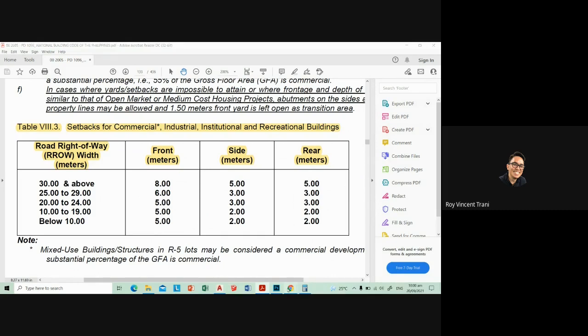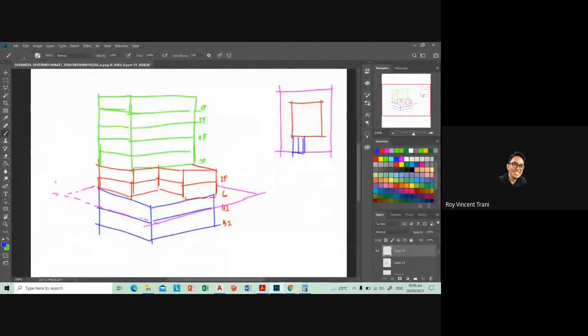But as we mentioned last week, let's say Bilaran Road is here. I'll just call it B Road and M Road. So Mindanao Road and Bilaran Road, this avenue, should be treated as a frontage, as a front. Therefore, our setback, I'll just change another color, over here should be 5, over here should be 5, and on the sides will be about 2.